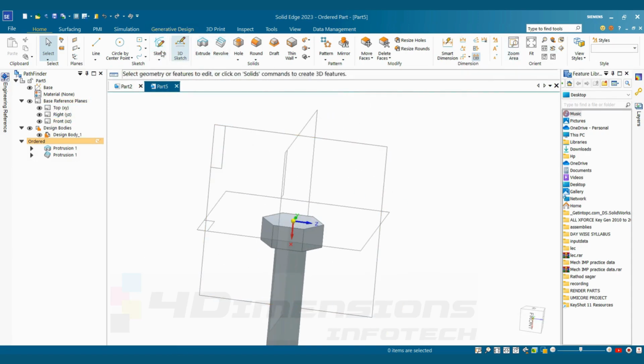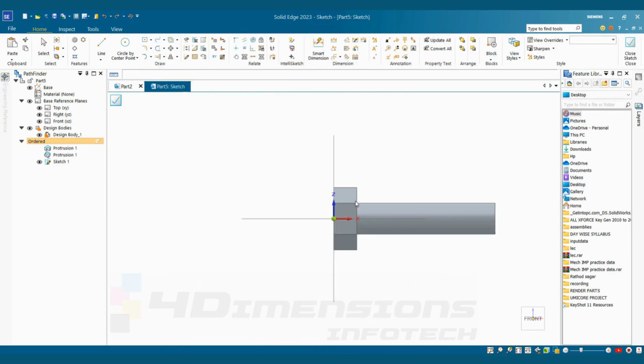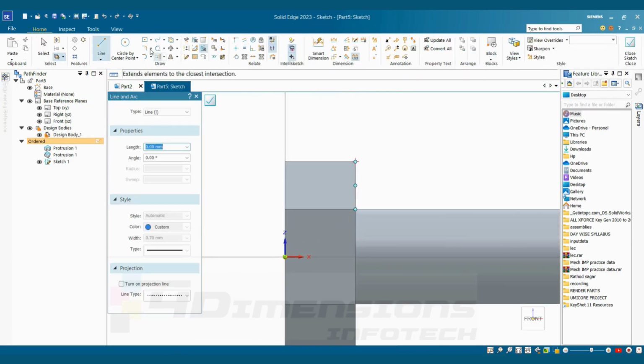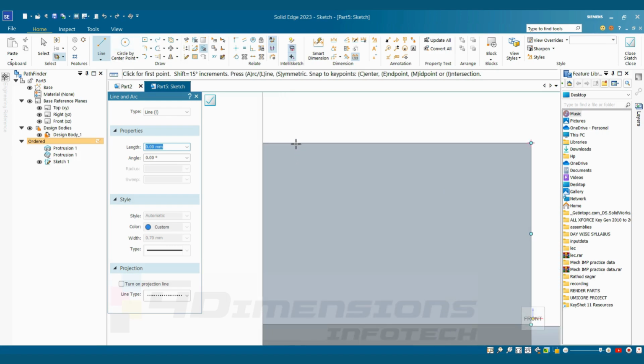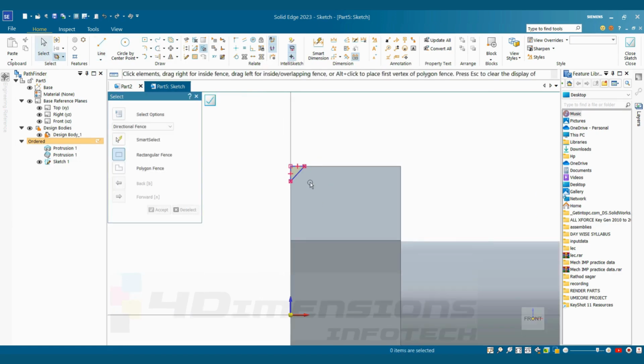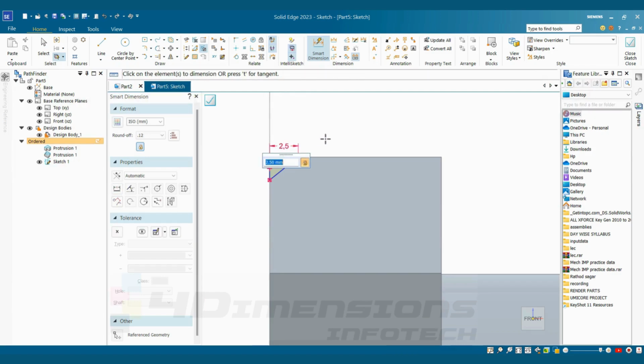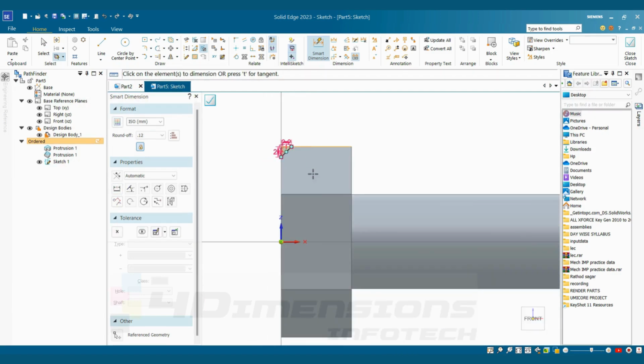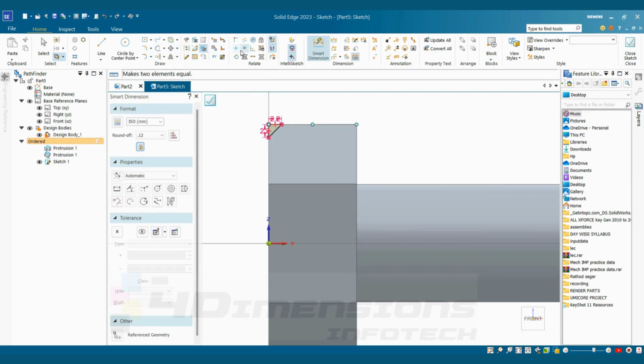So select the sketch, select the plane to be sketched, and we'll make one profile for the revolve cut. I'm going to go for triangle here at the corner side. It is compulsory for making this sketch on the corner only at this cross section. Dimension we are going to give here is 2.2 on both the sides. Now we need one axis also here, so as to revolve cut.